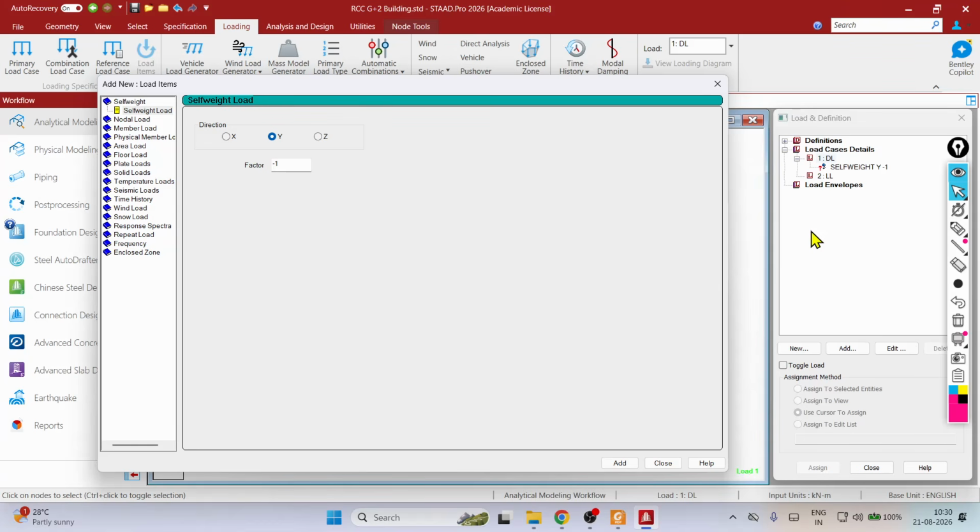So height is already 3 meter. So we have to convert this 230 brick work into the dead load on our beam. It is going to be brick load on our beam. So height is 3 meter, thickness is 230 mm, it means 0.23, and the density is 20. So how much value would be there? In kilonewton per meter, when you multiply, it is nearly about 13.5 something. When you multiply all this.